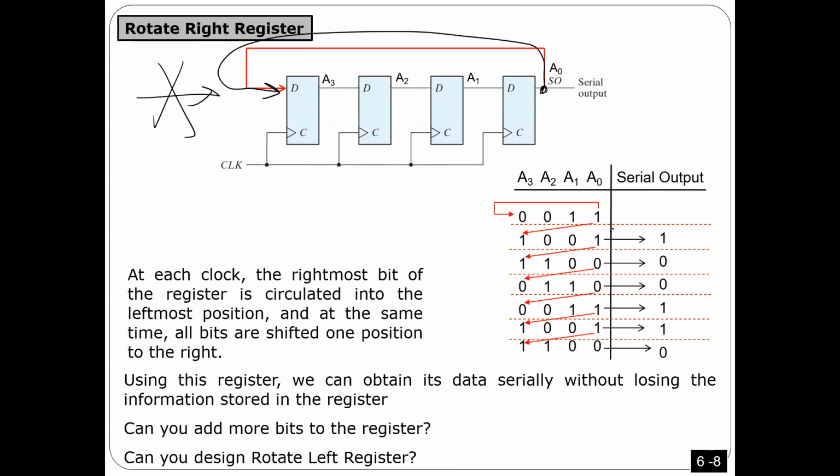And again, you may wonder how this is useful. Yes, it is useful, but I can't tell you now, because when you read a system, you may need something like that. So you rotate the bits this way every clock. As you see here, this bit comes to here and everything is shifted to the left. You're not going to input any new bits, and you're not going to lose any bits. You just rotate them. That means after 4 clocks, you're going to get the same number back. Look here, this is 1. After 4 clocks, I get the same number because I rotated all of them.